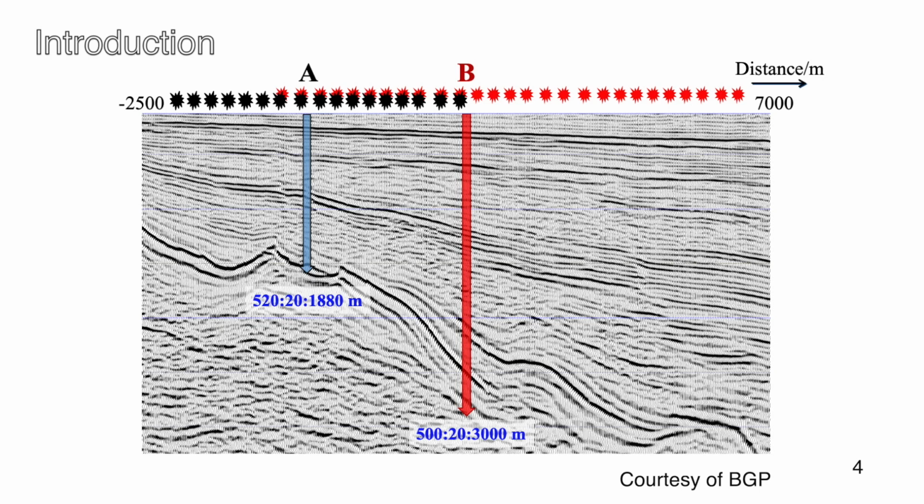In this talk, we present the survey carried out at well B to show the dipping features of the basement top. There are a total of 267 shot locations with an interval of 25 meters on average. The geophones recorded 6 seconds of data at a total of 126 levels from 500 to 3,000 meters measured depth. The surface offsets reach 3 and 4 kilometers on either side of the well.